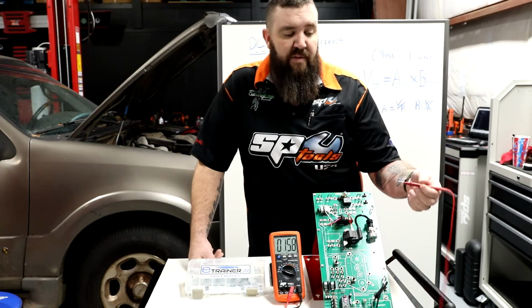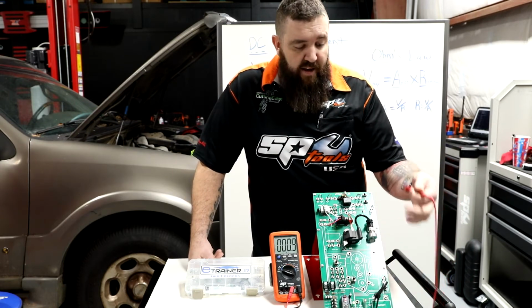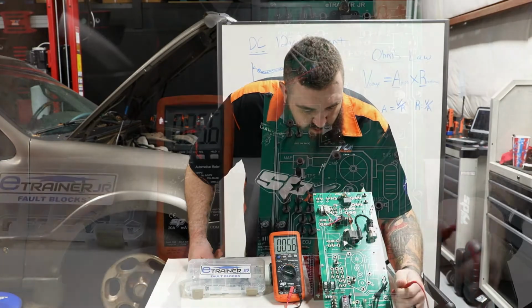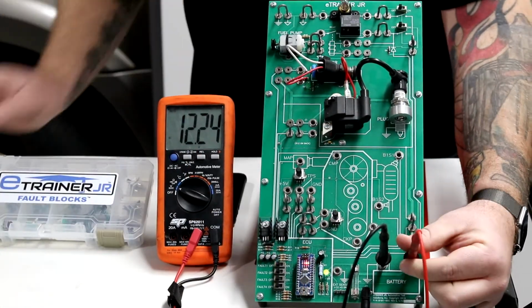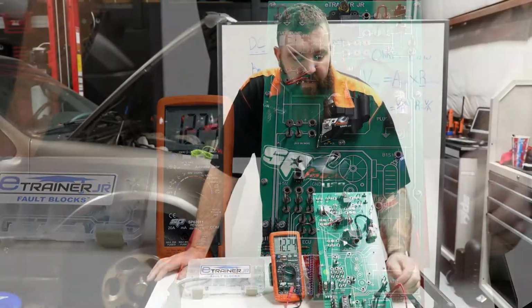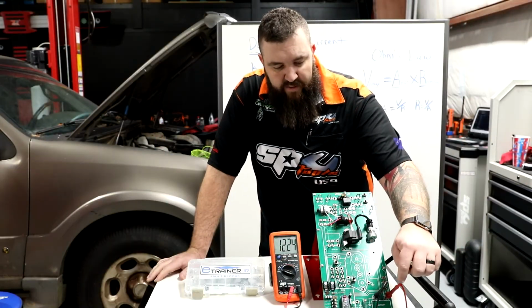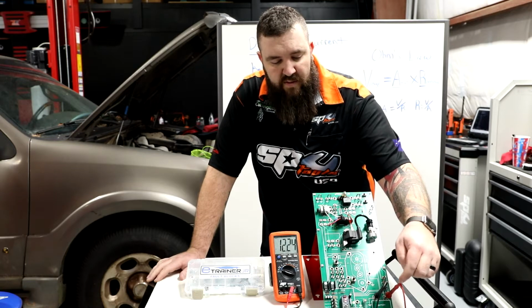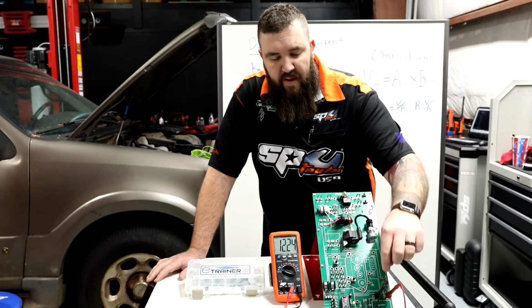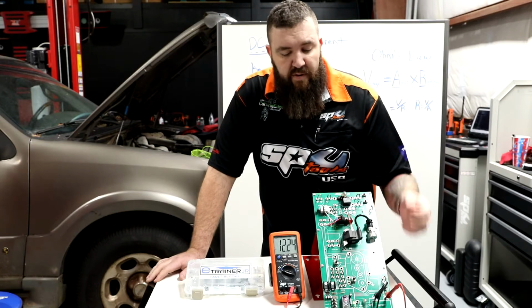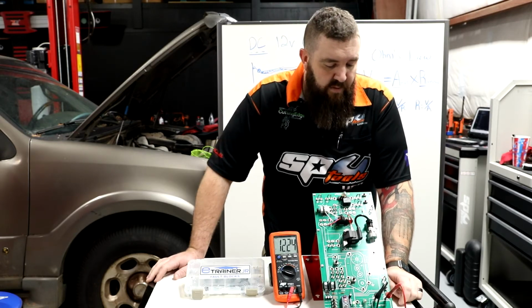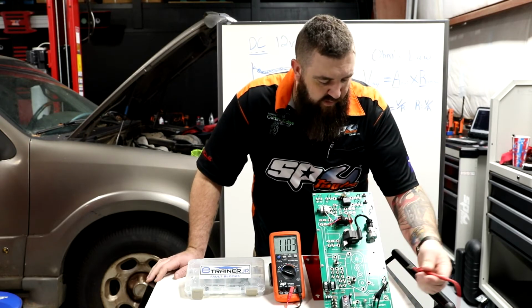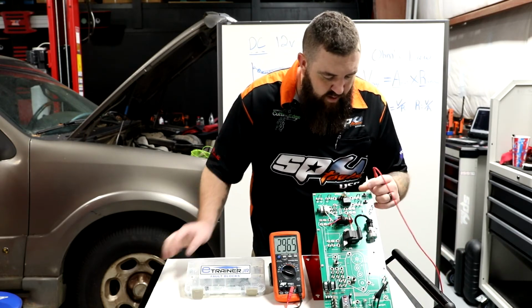Now we want to be able to find out what our voltages are at certain points in the system. We know, testing a good battery right here, we're going to be at just over 12 volts. So that is taking our positive reading, which is reading 12 volts. And after it goes through the system, it pretty much reads 0 at ground. So that is why our meter reading is right at the 12 volt function. So we're going to go up into the system a little bit further, and we're going to turn on a light bulb.